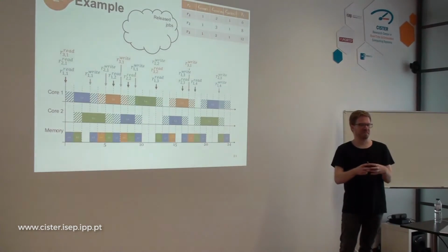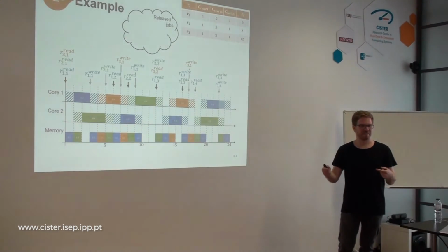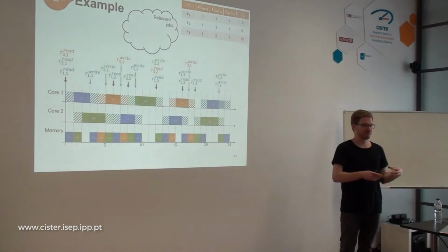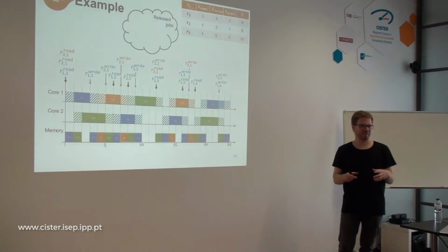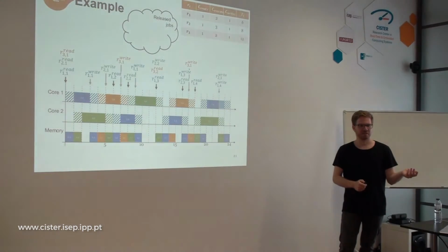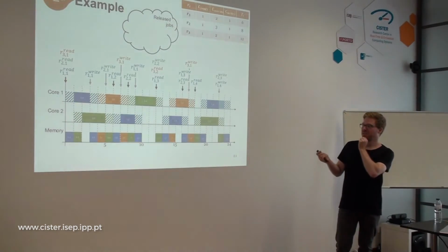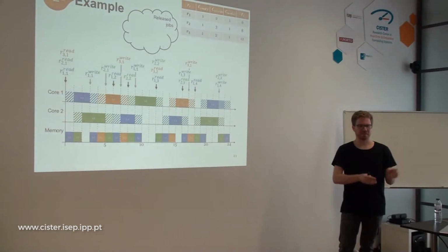Yes, that would be a nice approach, but you could also just group runnables together and form these groups of execution. Because usually the footprint of the runnable and the labels is much smaller than what we can fit into one bank. So we could put them together, form bigger entities, and then fill up the banks completely, so we don't pay as much for accessing the off-chip memory. And then you would circumvent this. What I showed in the experiments, this 5% is also quite a lot. So usually we are more on the smaller side.